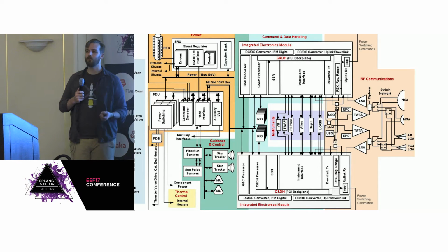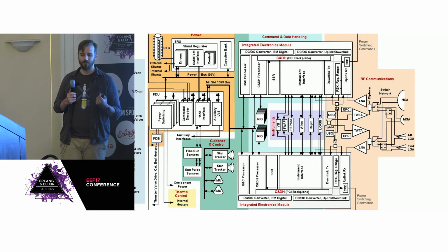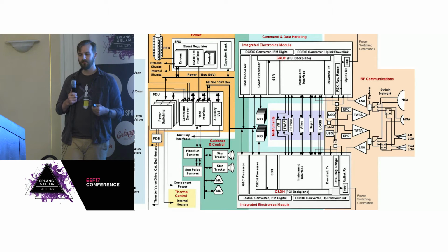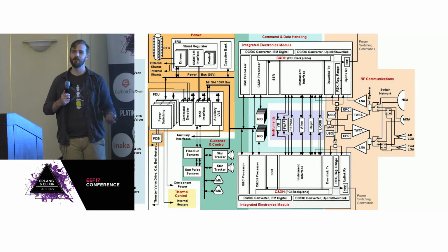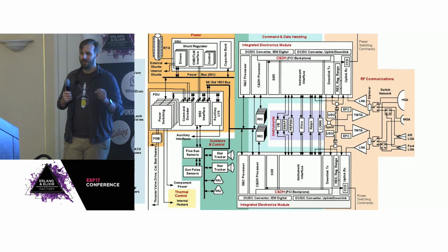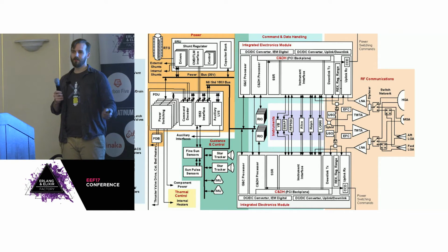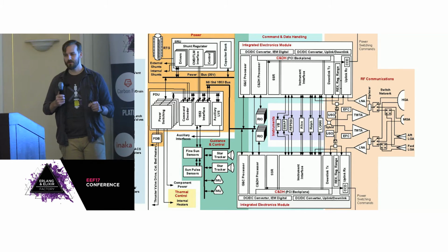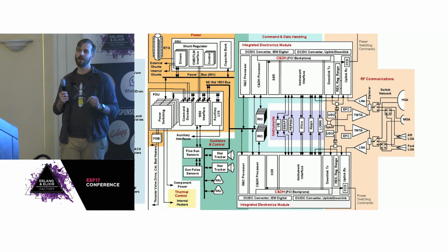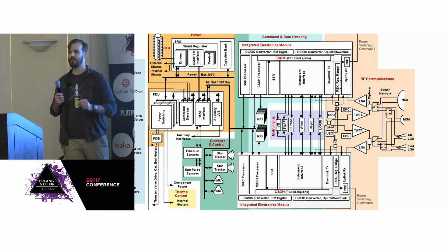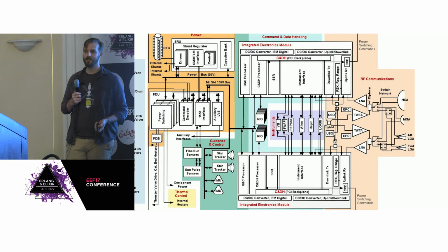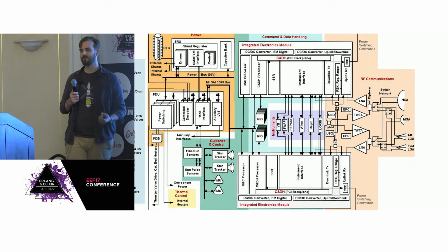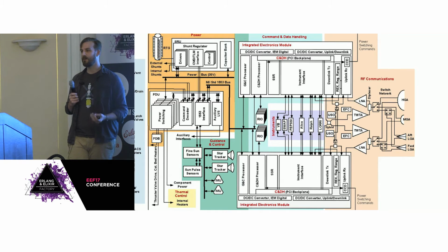New Horizons is a really weird computing environment. If you're going to get irradiated in the solar system, the first place you're going to get irradiated is in the orbit of Mercury. If you go basically any further in, you're just going to get vaporized, and I don't know if you can rightly call that irradiated. If you want to get irradiated, but you don't want to go near the sun, fly past Jupiter. Jupiter is a pretty radiation-harsh environment, and New Horizons had to do a gravity boost around Jupiter, so it got irradiated pretty hard when it flew around. So the processor inside of New Horizons has to be what's called rad-hard. It has to be able to survive a radiation-hard environment.